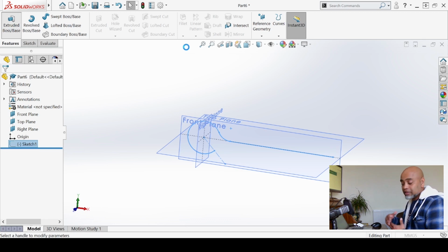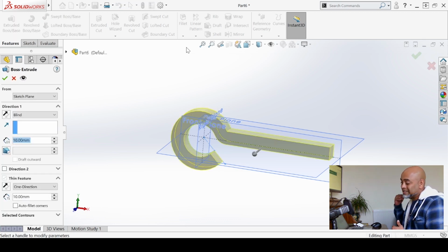Every time you feed SolidWorks an open profile, SolidWorks will try and create a thin feature. Okay, that's a technical term, thin feature. It doesn't have to be a very thin feature. You could apply a certain thickness. Now all I did is I clicked into Extrude Boss Base. SolidWorks threw no complaints at me, and it just, like a puppy, tried to create a solid based on the sketch I had provided. What's going on here then?